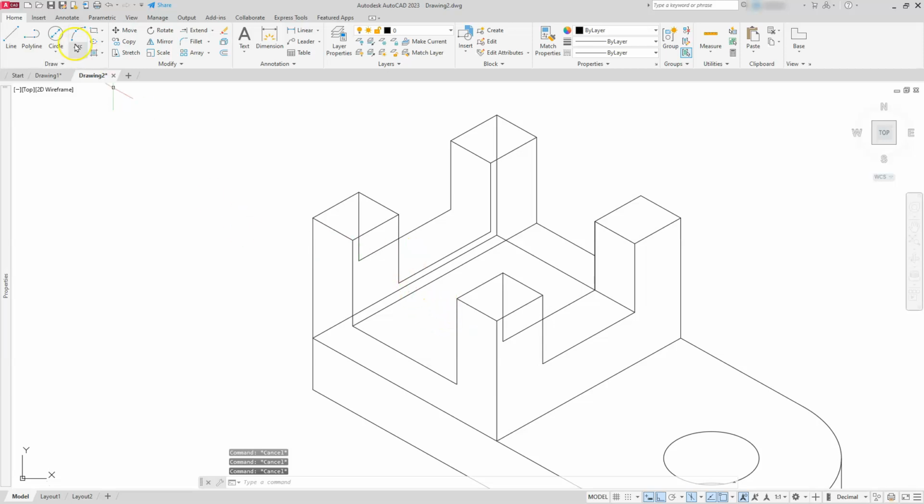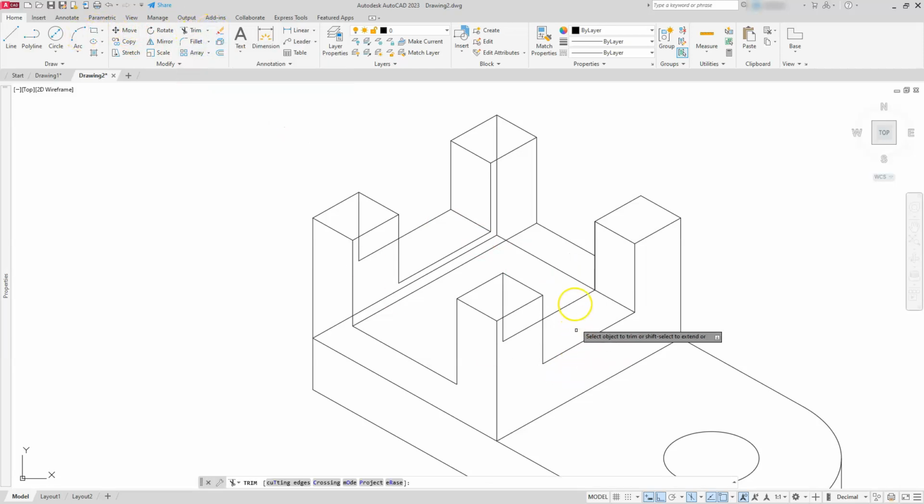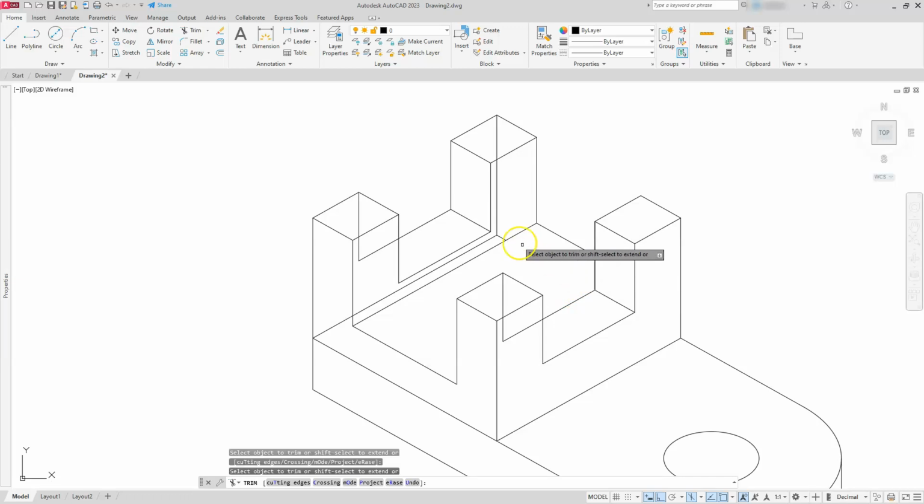Alright, now I can start seeing things a little bit more clearly. Just going to connect the line going right across to here. And we're going to start erasing some lines, and things are going to really become clear here in a second. Use the trim command next. I'm going to trim off this portion, even this little bitty line here. I'm going to get rid of all this on the back side. I'm going to walk this line back, and we don't need to see that at all.